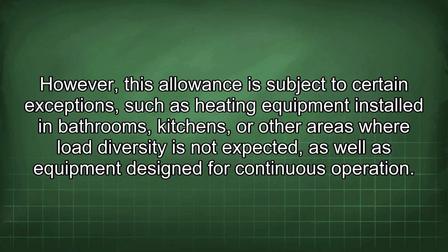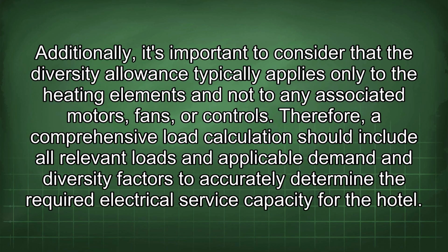However, this allowance is subject to certain exceptions, such as heating equipment installed in bathrooms, kitchens, or other areas where load diversity is not expected, as well as equipment designed for continuous operation. Additionally, it's important to consider that the diversity allowance typically applies only to the heating element and not to any associated motors, fans, or controls. Therefore, a comprehensive load calculation should include all relevant loads and applicable demand and diversity factors to accurately determine the required electrical service capacity for the hotel.